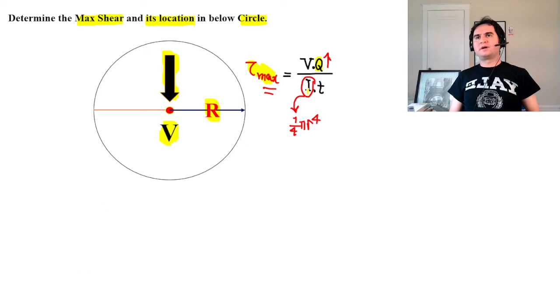I for a solid circle is a quarter of pi r to the power of 4, and just assume capital R and lowercase r both stand for the radius. Whether a numeric value of shear is provided, or it's given parametrically. The thickness is considered at 2r, a diameter.